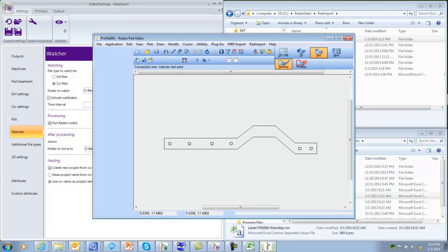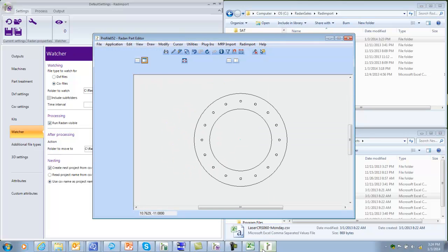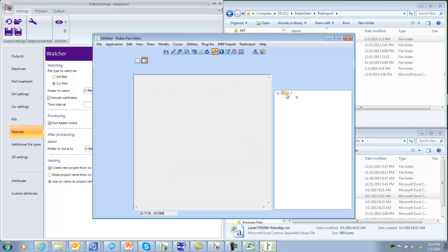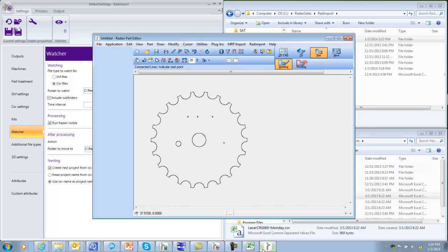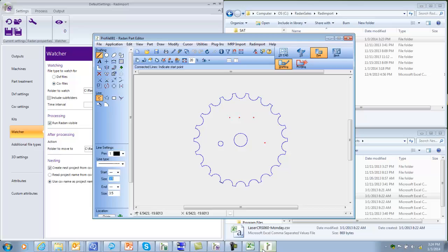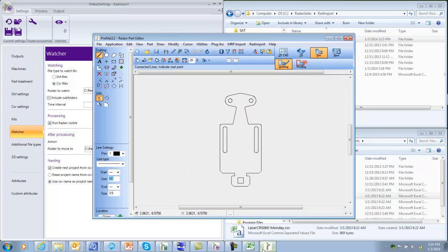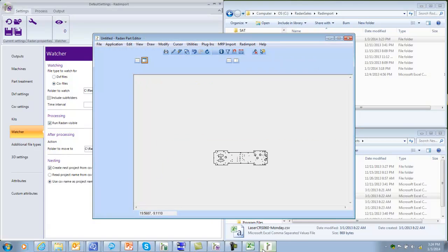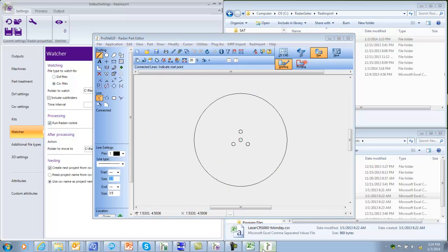It's also applying a temporary laser toolpath here to do some time calculations for us so we can get some runtime information about these parts. And it's saving them as a Radan sim file, which is the format ready for nesting in Radan. I have some automation features turned on where when it's finished reading in the CSV file, I have it set to go ahead and bring it into a project and then actually start nesting the parts. So it's going to take it the full length here.